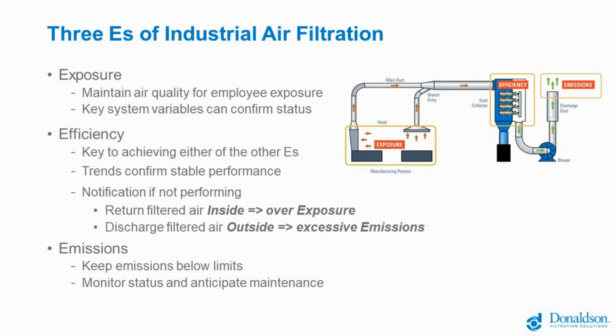Performing ongoing monitoring of your system, such as maintaining the design flow, tracking the filter life and the filter loading, and detecting the early onset of filter leaks, will help monitor the overall system and its status, and thereby reduce the risk of unplanned operational downtime.